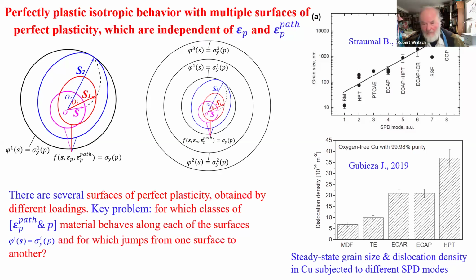As a follow-up, I'm wondering if the dislocation density is still very high, it will want to recrystallize, maybe by Ostwald ripening, and lower its internal energy by producing a new product phase out of equilibrium with its hydrostatic pressure field. I know in geologic materials, amorphous silica can produce metastable phases in between that and quartz, just by lowering the internal energy, but not lowering it to the minimum. Is that possible in some of these experiments?